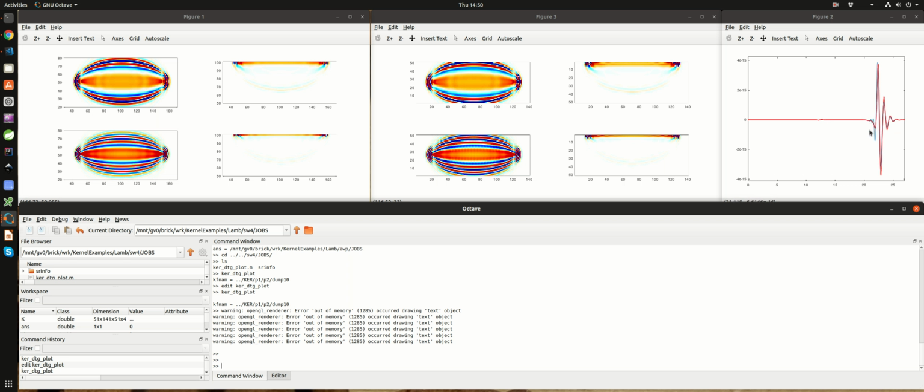So suppose I add a refinement in the input file, right? I can refine the grid from like 50 meter to like 25 meter. If I do that, these small oscillations in front of the Rayleigh wave are going to reduce, right? And if I reduce the grid spacing by another factor of 2, to like 12.5 meter, then this oscillation is going to become even smaller, right?